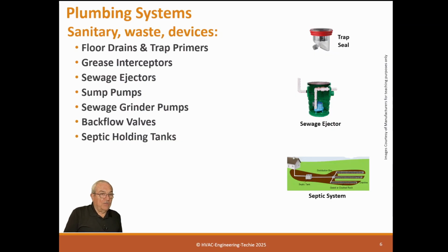And then we have septic holding tanks. If you either live in a residence or your commercial building is such that you don't have sewer systems in the street, you'll have to build a sewer system. To do that, we use a septic tank as a holding tank. Basically the sewage comes into the holding tank, and this separates the solids from the fluid. The fluid goes out to a field, which has gravel and trenches in the ground, and it will then seep into the earth from there.